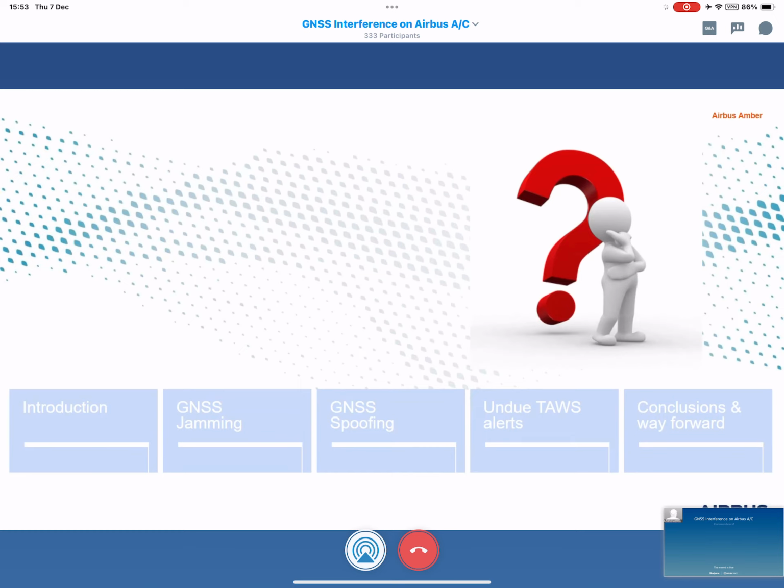So for the time being, what we can say is that the GLU 2100 is not affected by the lockup issue which is described for the 925. However, it's still susceptible to the general impacts of the GNSS RFI. It is, yes, expected to be more robust against certain problems observed in previous MMRs, but it will, of course, be lost temporarily during GNSS exposure.